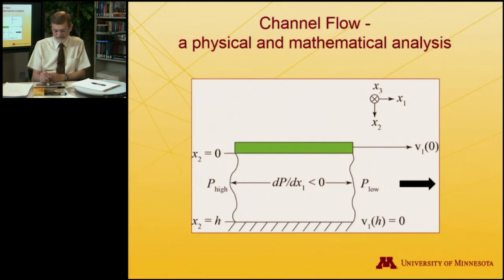So that's the height or the depth of the stream or the depth of the channel that we're talking about. And the velocity at the bottom is 0. Right? We'll say there's a no-slip boundary condition. So the fluid is stuck to the bottom, the stable, non-moving bottom of this channel, whereas the top can move. So there's a velocity gradient. The velocity is high at the top, and it's low at the bottom, and it's somewhere in between as you go through the channel. And it's that behavior that we want to talk about today.